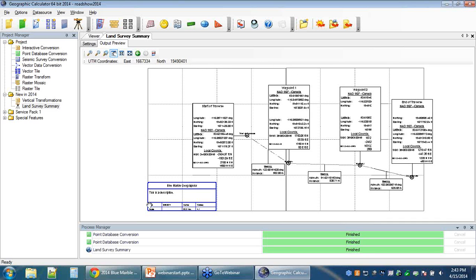The context of the map frame that we have here, we can see our traverse actually goes across 2 townships, so it has included both of those townships for me on the view. It will expand to however many of those you need. The location of all of the text boxes is smart placement. They will simply try to avoid colliding with each other, preventing overlap from any of those. Tries a number of locations till it finds something that does not step on the toes of another box. All of this is automatically generated.